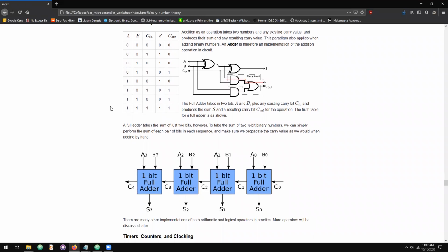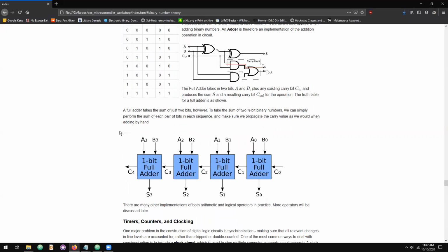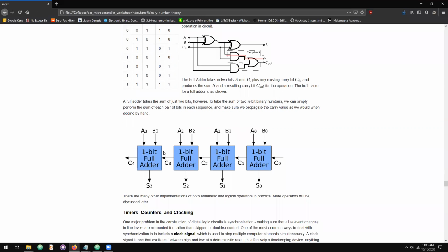And the way we can extend this into representing binary number addition is basically just by chaining them together. So you take the carry value of one of these full adders. It has some carry input that is provided to it by some system on top. It has our 2 inputs. We do the full addition.